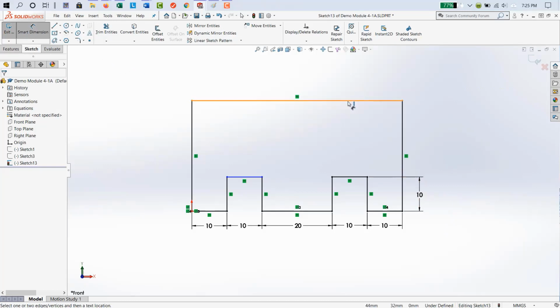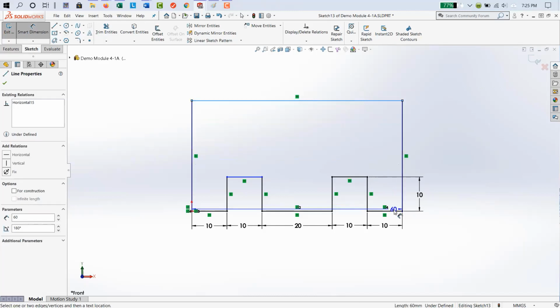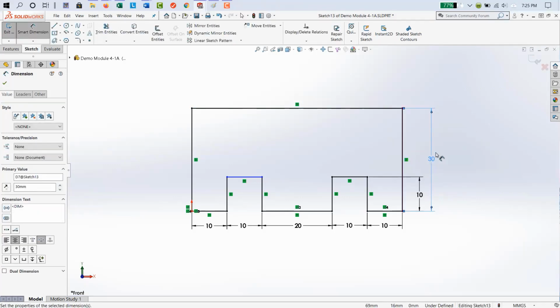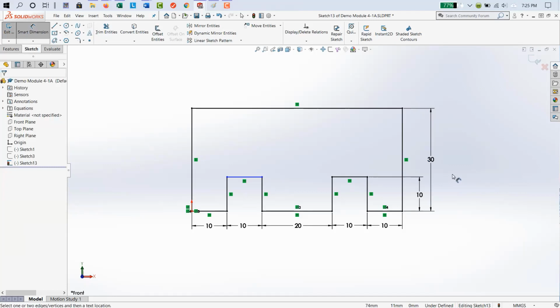Now I'm going to set the next dimension for the overall length of that side. And notice with that one, I can go about half the distance as long as there's no interference with the dimension value and it can be clearly seen. Now, if the middle just happened to be like right here, then no, we're going to have to make sure that we put enough distance so that you can see the value. You must be able to read the values. So all of the dimension rules are available for you in the handout.